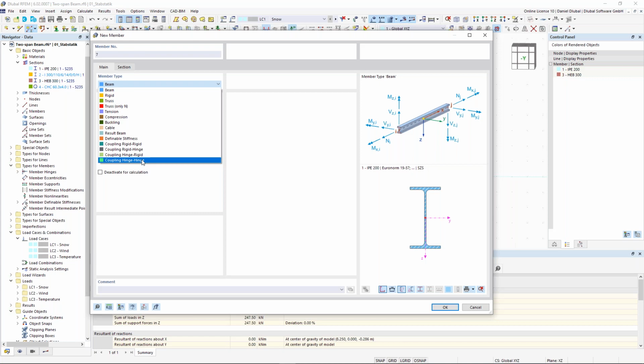But this is not an easy task, or rather not a difficult one, for a structural engineer who is more familiar with the consideration of these existing structures. In general, as a structural engineer I would first calculate with the existing structure, and then in a second step neglect the existing structure, considering only the newly added structural elements. This would be my approach.